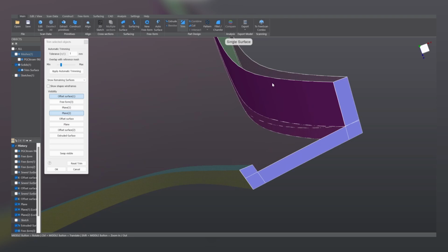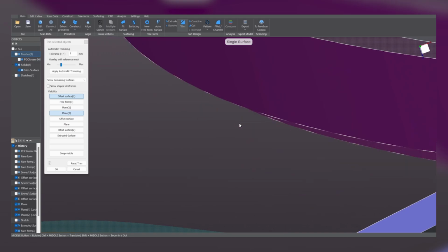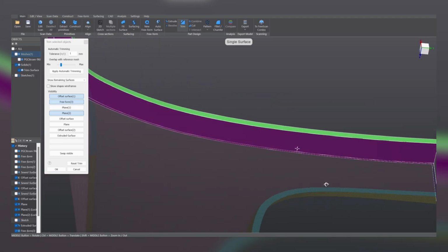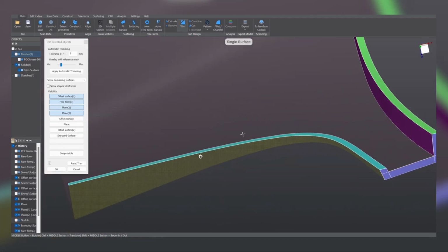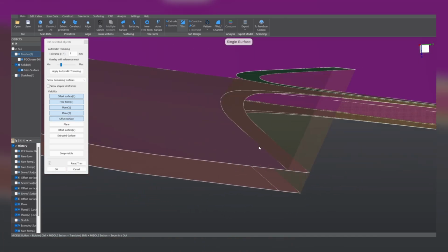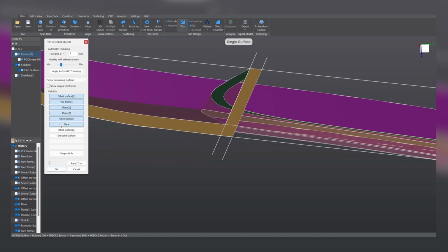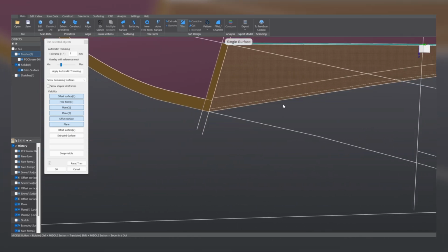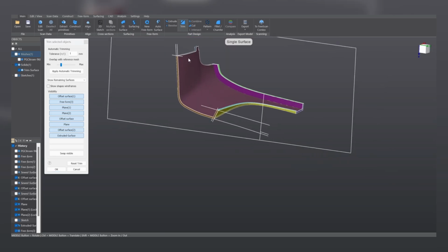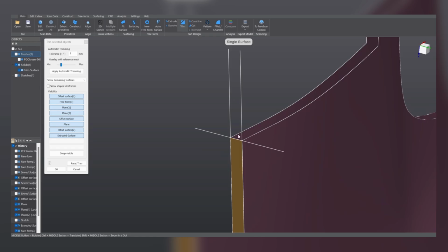Here we have exactly the same problem that we described. The surface on the left is going into the volume of the solid, so delete these faces. Okay, this looks clear. This plane looks good, no problems with it. The offset surface, watch out, it's going into the volume, so we need to delete this region. The plane here is well defined and well trimmed. Same for this offset, and well, we have this extruded surface, which unfortunately leads to this problem, right? But we are gonna solve it now.